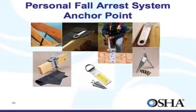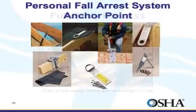Here are examples of various anchorage devices. All anchorage points must be capable of supporting at least 5,000 pounds or be designed and used under the supervision of a qualified person and maintain a safety factor of at least 2.